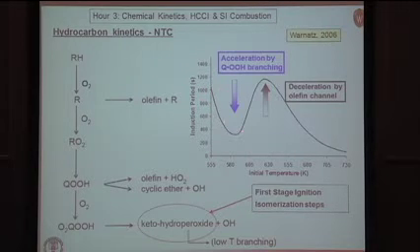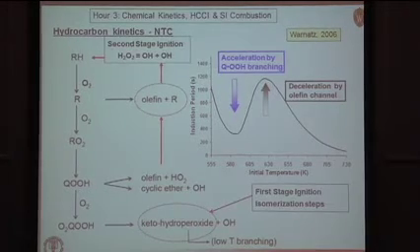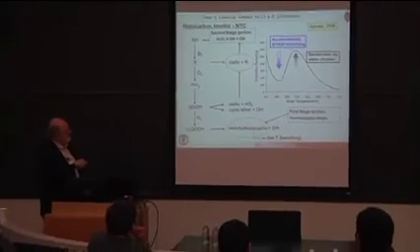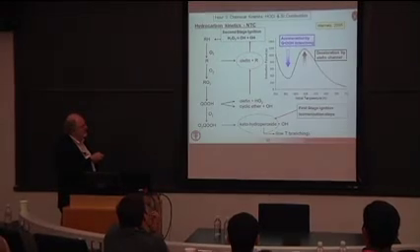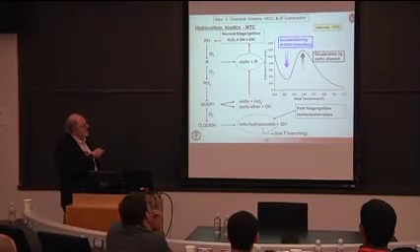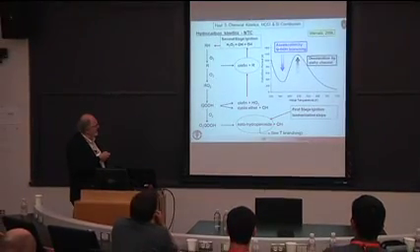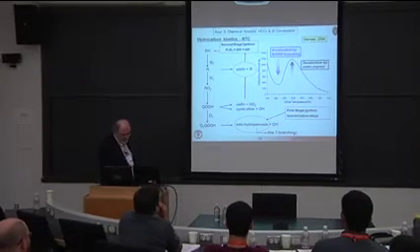This acceleration or reduction in ignition delay time is due to these low temperature steps. As the temperature increases, though, another path becomes more important, and that's the olefin path here, which essentially takes over from this. And eventually, when the temperatures are high enough, we see again the hydrogen-oxygen combustion taking over, leading to the high temperature combustion.